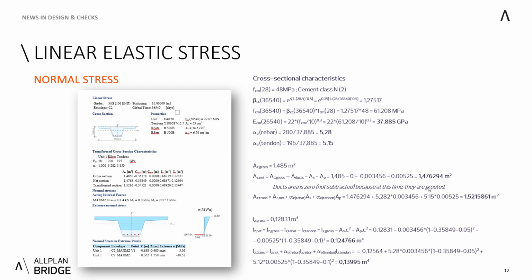And to explain the numbers, or to verify them, we need to start actually with the materials. So we can take a mean strength of concrete at 28 days, which is according to this specifically selected C40/50 concrete grade, 48 megapascals.